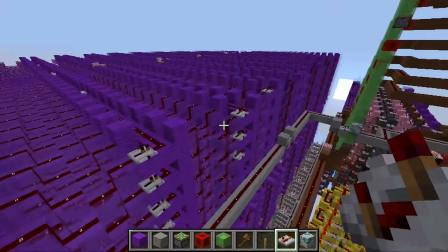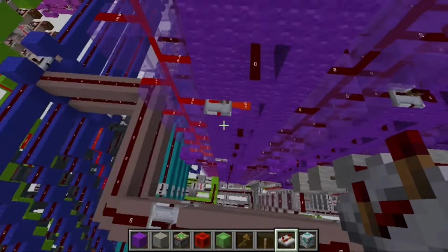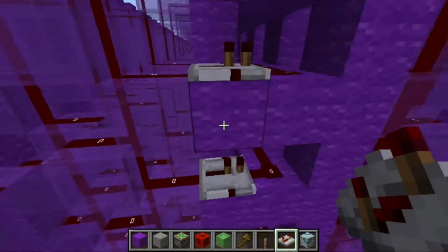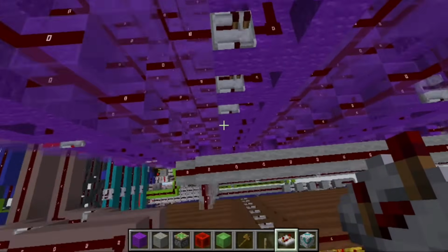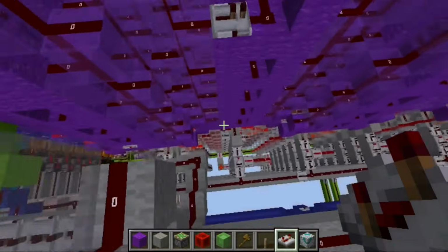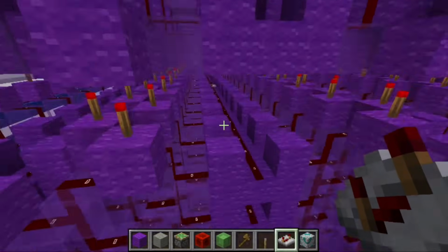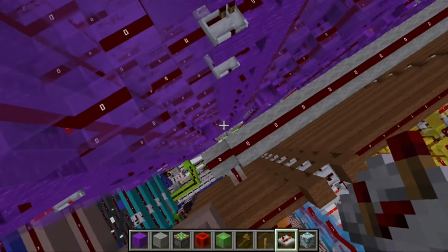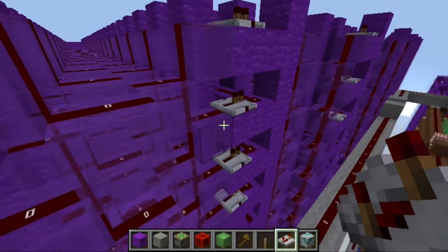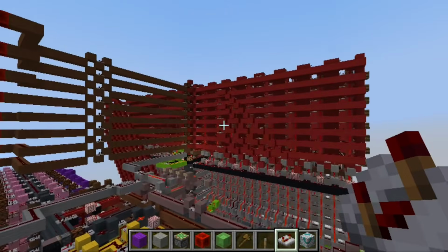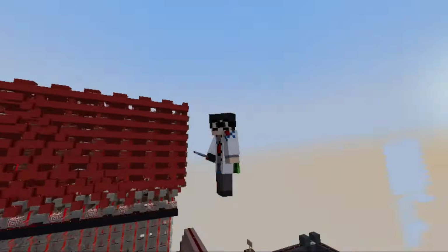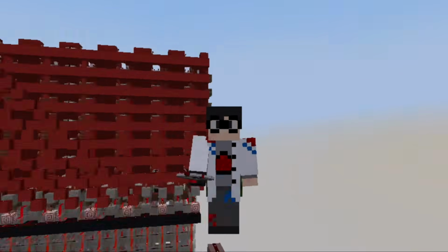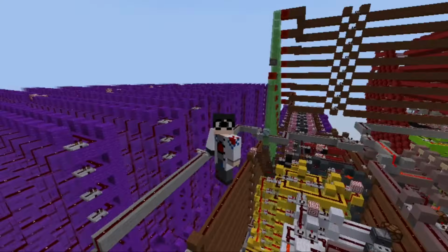There are in total 4 instructions here. At address 0 we have load R1, and we load a number 1 in. And at instruction number 2 we have store R0, R1, and 0. What this means is we are going to store the data at register 1, and we're going to store that value into memory R0 plus 0. Since R0 has the data of 0 and the offset is 0, we're going to store the data at memory 0.